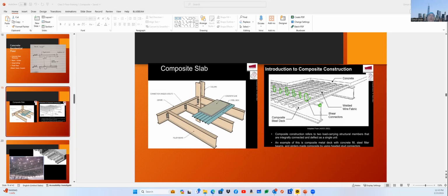So you're probably already aware of it. I will explain with a simple beam. We are talking about a T-beam. Since the slab and the beam are tied together, even though, let's say, a concrete slab and a steel beam, glued together with the shear stud, they work like a T-beam, which is much stiffer, which means we can optimize the steel shape. It's mostly because of structural efficiency and being stronger, so that we can save more steel.